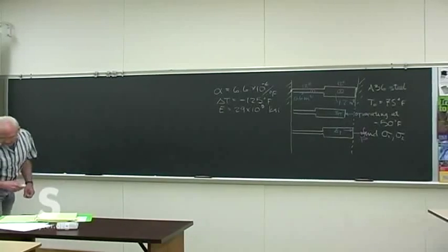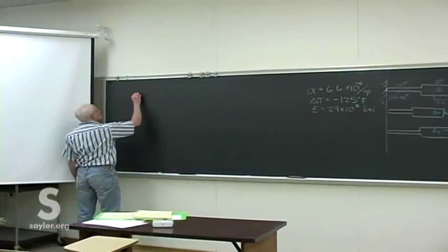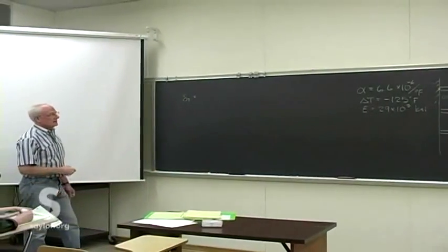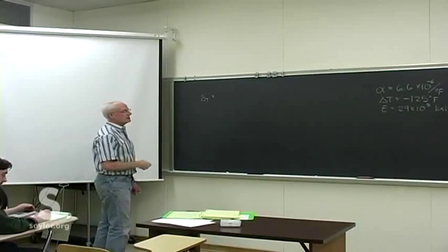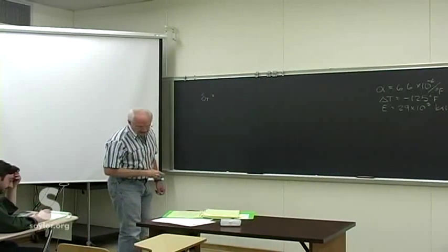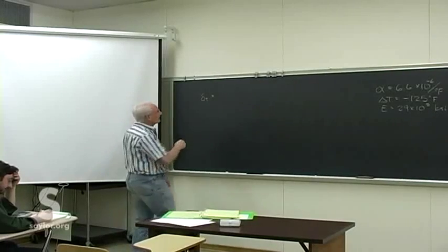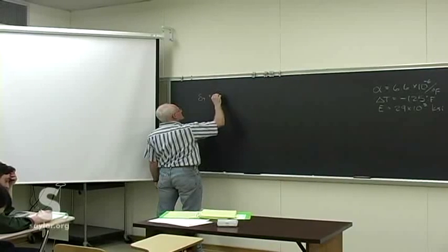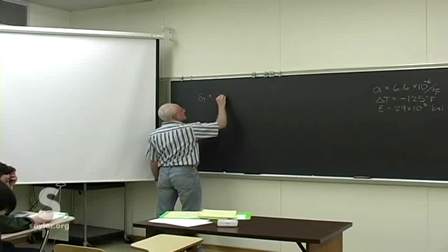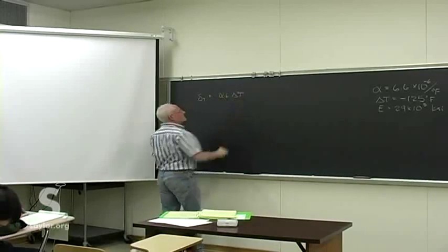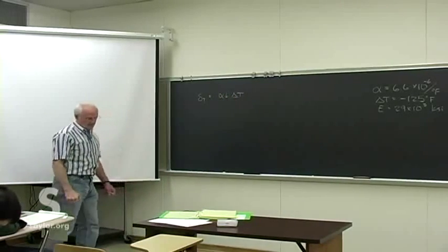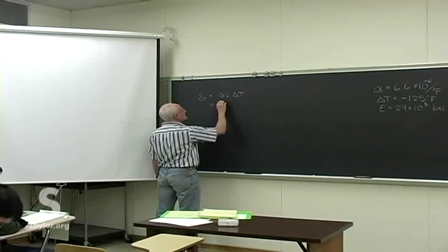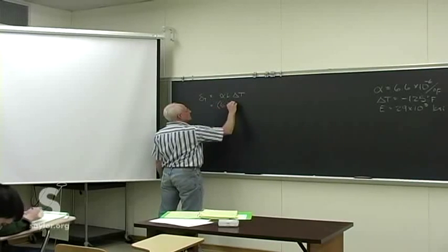All right, so we can figure out the thermal change in the pieces that we expected. This is the length they would change if they were free to do so, but they're not because of the attachment to the extreme pieces, or to the support pieces. But that's the business we just looked at, alpha L delta T. So we've got all that. It's easy just to put it in and observe what the expected change in length would be.